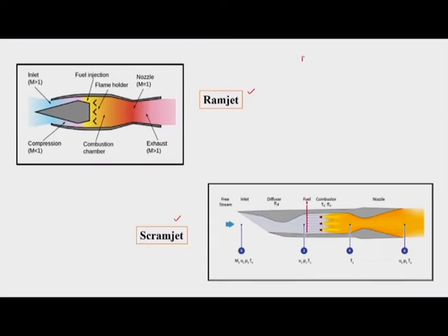Then in the case of ramjet and scramjet, we take advantage of an effect called the ram effect. Here the inlet momentum of the air is used to increase its pressure. So, we try to increase the pressure of the air with its own momentum. This is what the ram effect is all about. In general, using this effect, the effectiveness or efficiency of an intake is defined as ram efficiency. But before that, we will revisit the ramjet and scramjet intake.